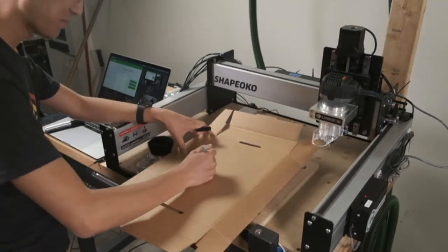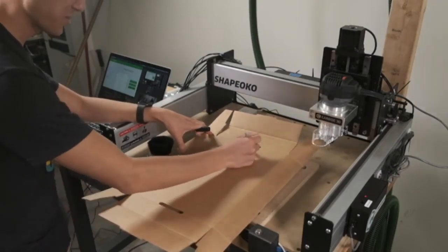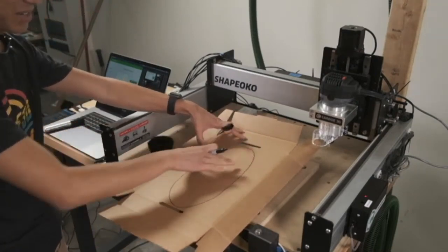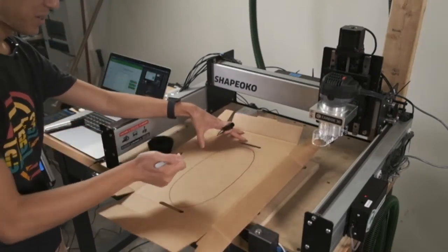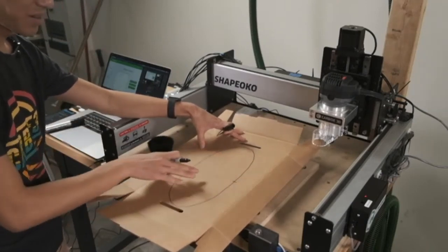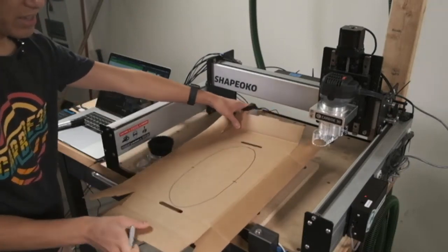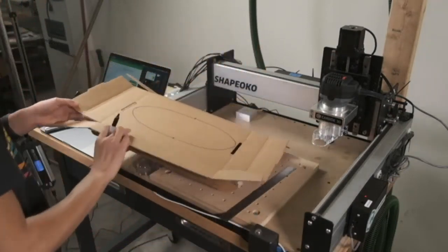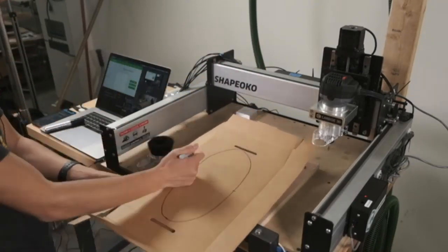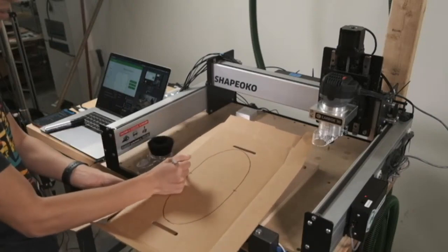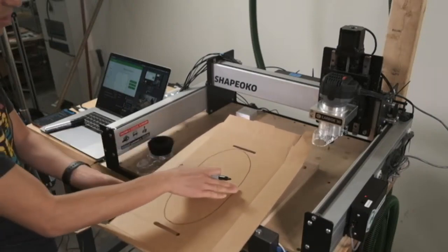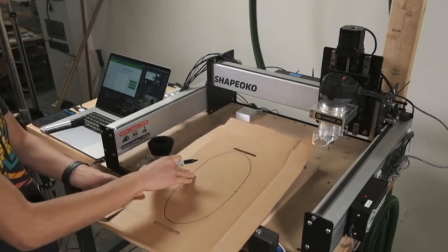So let's say you're trying to cut out that oval that extends past the cutting area of your CNC. You'd have to find some way to partition the toolpath to stop it somewhere so that you can then reverse that workpiece or slide it forward and backwards, reacquire a 0 coordinate, and then use that coordinate to determine where the rest of your toolpath will fall.